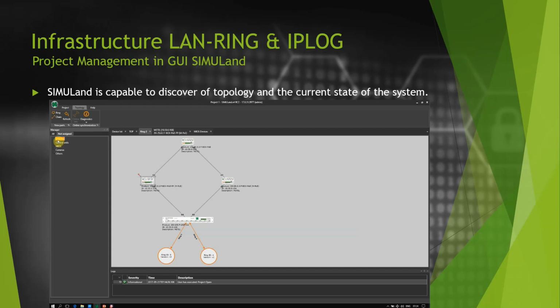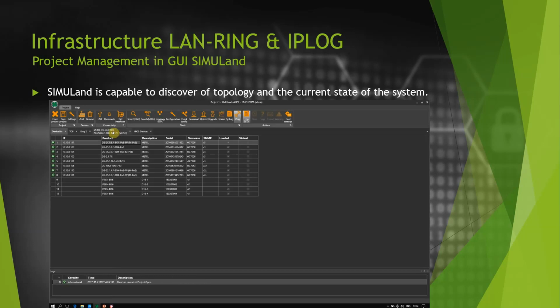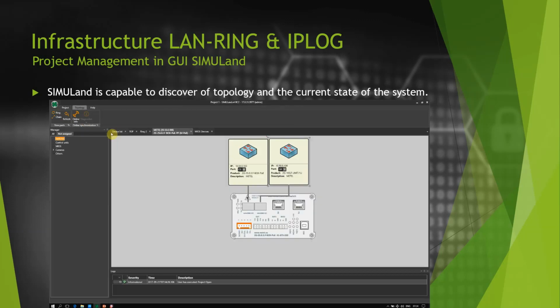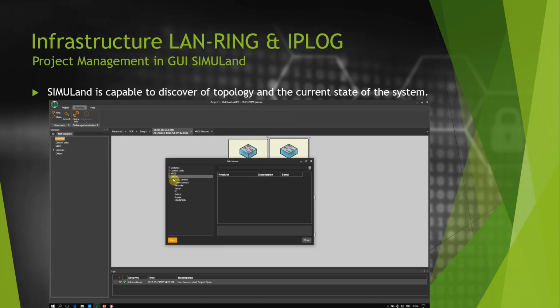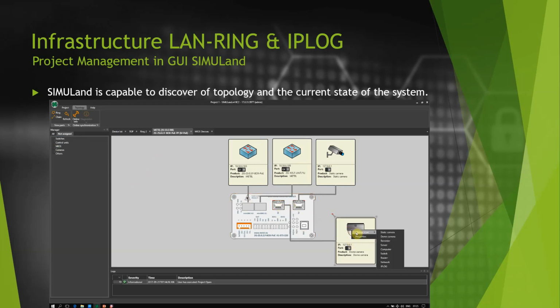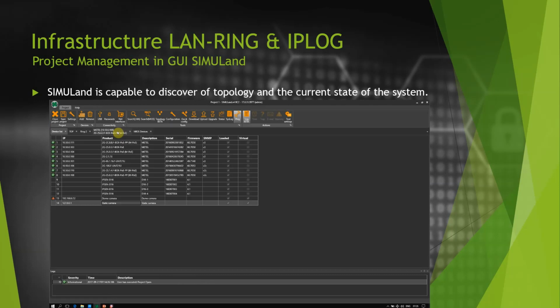Third-party objects such as cameras, servers, computers, but also all METEL devices are added to the project using the Add tool in the main taskbar, or by right-clicking on the device port at the lowest level, Detail, using the right button. You can directly assign the device without the need for a manager. If you add a device using the Add tool, you must place it from a manager and then connect it to a given port. For these objects, it is also possible to change their icon. Deleting a device is only possible from the device list.